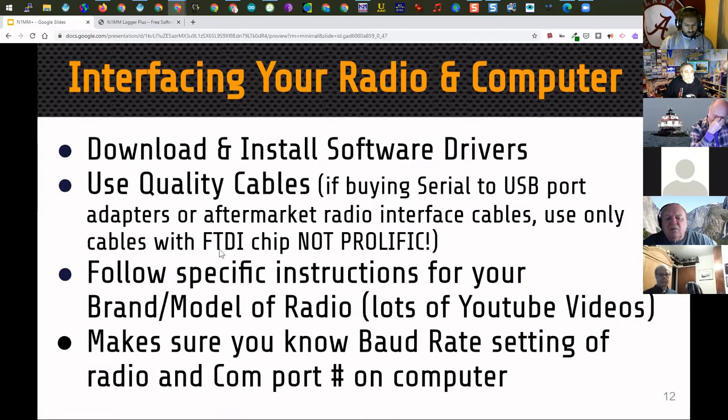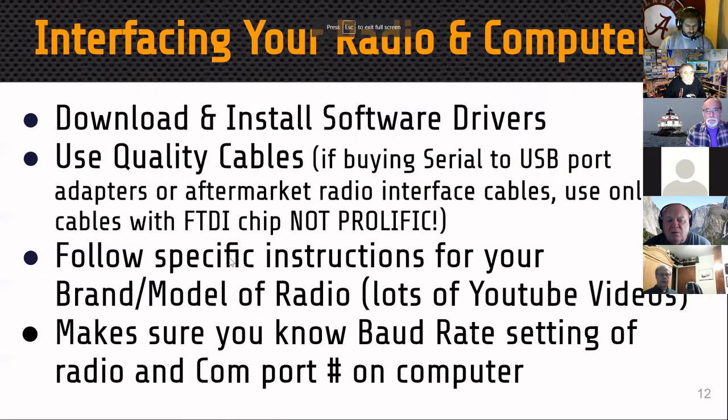I also mentioned in this previous slide that if you're buying new interface cables, look for the FTDI chip in it and not the Prolific chip, which seems to have a number of problems with it. So again, those are just some hints.